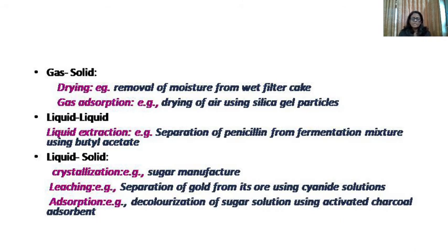Coming to the last category, liquid to solid, here we have crystallization, leaching and adsorption. Crystallization is that operation which involves producing materials in solid form. It is the formation of solid crystals from a liquid solution.